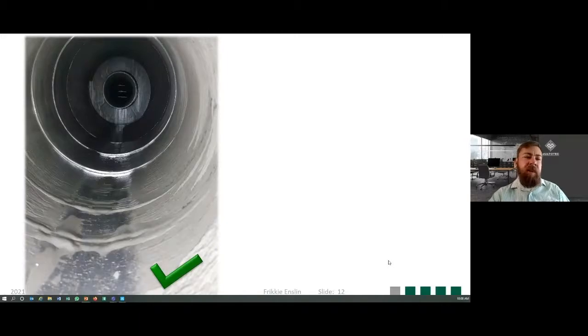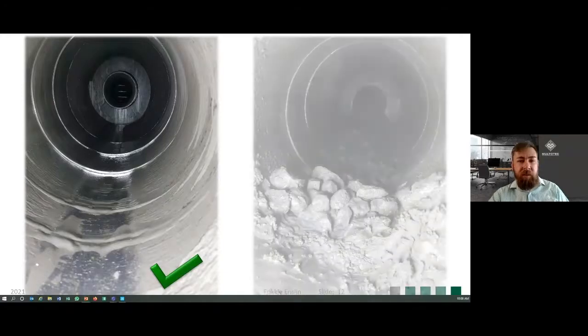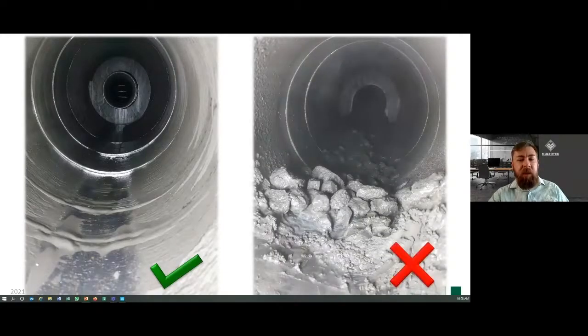There's the inside of a DMS cyclone in this case, where it's installed correctly, and you can see when the cyclone is shut down, it drains out and everything is fine. On the other hand, if it's not installed correctly, you can see that there's some trouble inside the cyclone. Now, those of you who haven't worked with ferrosilicon or with magnetite before, if that stuff gets hard and dry, it's like cement.